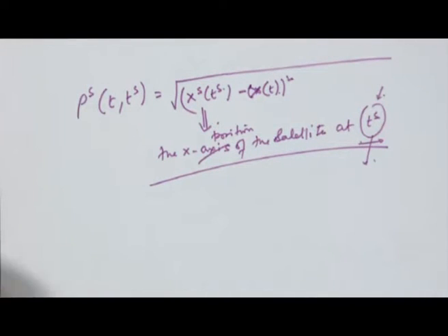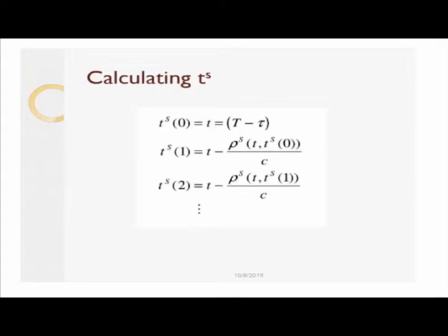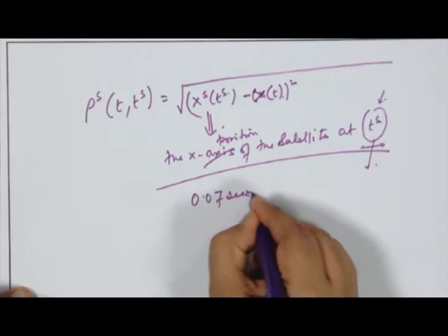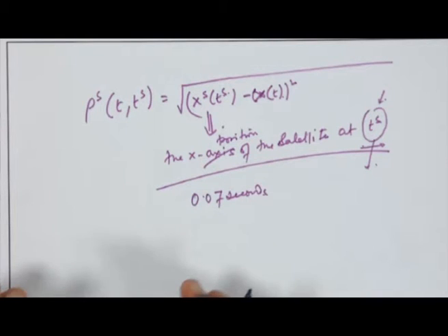Okay, so we note one complication, that the satellite position must be calculated at transmission time Ts. This is important because the satellite range can change as much as 60 meters from the time the signal was transmitted to the time the signal was received, approximately 0.07 seconds later. So if the receive time were used instead, the error computed in the range could be tens of meters.